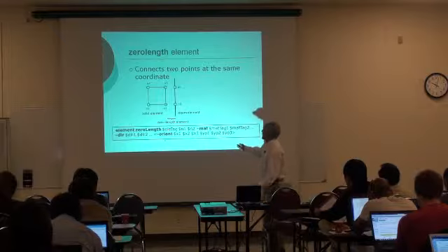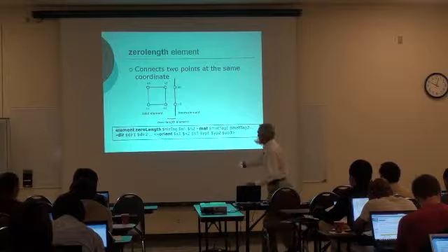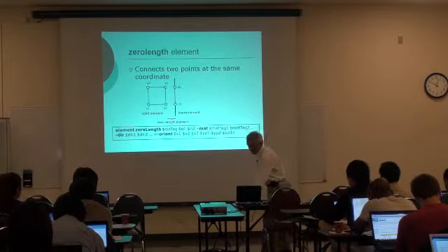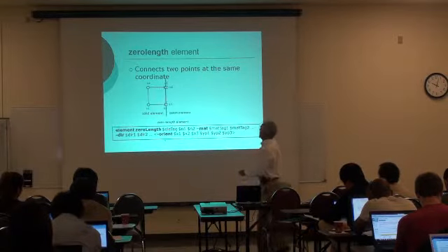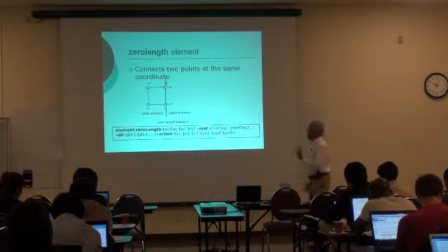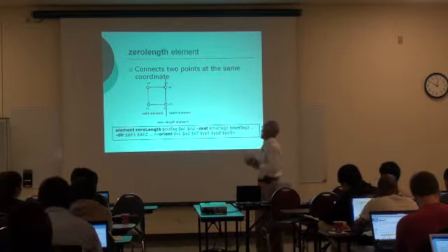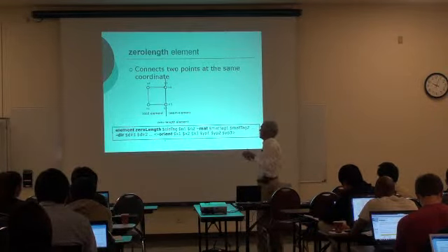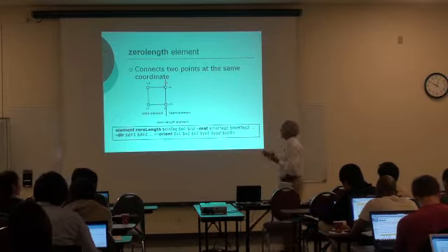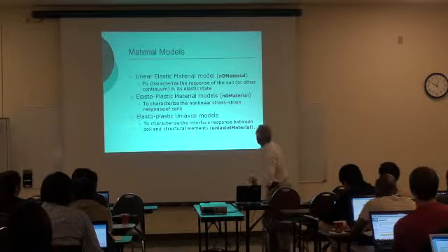And you have to define the type of material that will characterize that connection there, and in which directions these materials are going to be acting. So what you really are doing is to connect these 2 nodes that are in the same location with springs, and these springs can be nonlinear springs, and they can act in different directions. So if you're in 2D, you can have springs in 2 directions. If you're in 3D, you can have springs in the 3 directions.